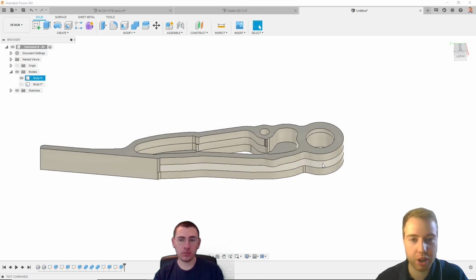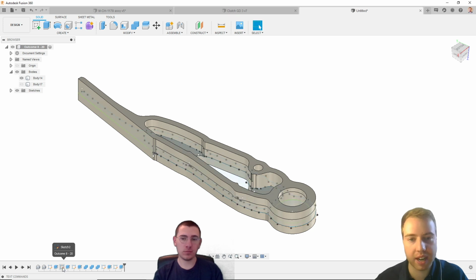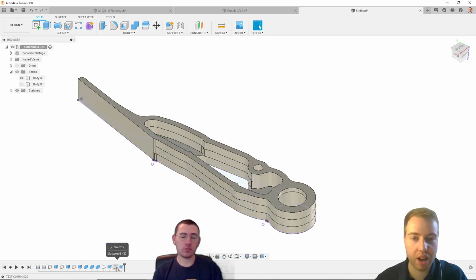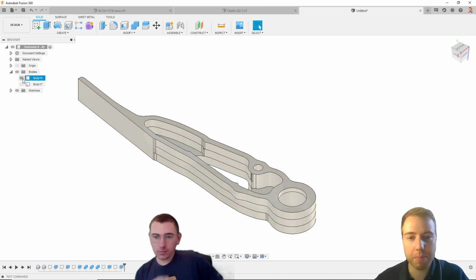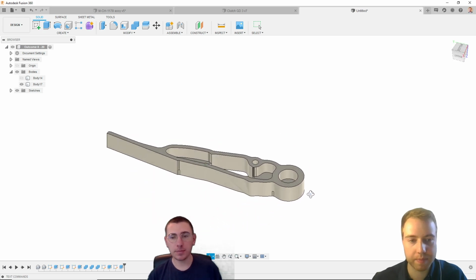We've got these two options. One option is, as we said, to take each layer of these sketches and edit one sketch at a time. And the other option is, by using that project tool and projecting onto a new sketch, we can edit the entire design at once.